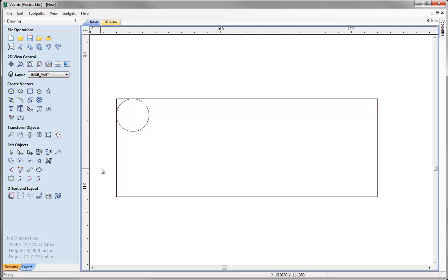So we have two options we can consider. We can manually finish off all of these mortise slots and tenon joints with a file to make a true mortise and tenon joint, or with the CNC machine we can use something called a dog bone or a T-bone fillet. What these do is allow the tool to slightly overcut into the corners, and then when it comes to joining these two mating parts together, they will actually fit.